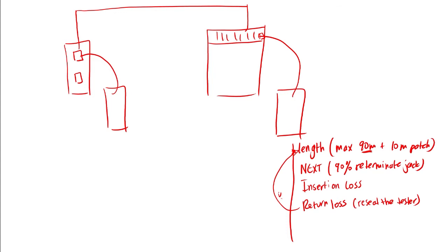And why do you have a cable that's longer than 90 meters? Well, sometimes you have to run the cable and you don't have a choice, because you may have a building where the only way to get all the cables short enough is to build a second server room, and that might not be cost effective. So technically it's wrong, but the client might say, well, we don't want to spend 50 or 60 or $80,000 to end up getting 6 cables shorter than 300 feet.